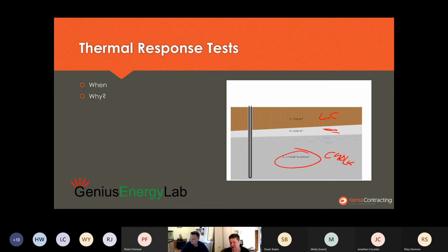So 1.7 to 2.8 is the type of variability we find in the chalk under London, which is watts per metre per Kelvin. It's a direct measure of how much energy we're going to get out of those boreholes. And it's one of the parameters we're trying to measure in the test. Because we've got various different levels with different conductivities, and various different conductivities even within the types of strata themselves, a conductivity test will allow us to measure, first of all, the thermal conductivity, also the undisturbed ground temperature, and really importantly, it allows us to establish what the drilling conditions are.